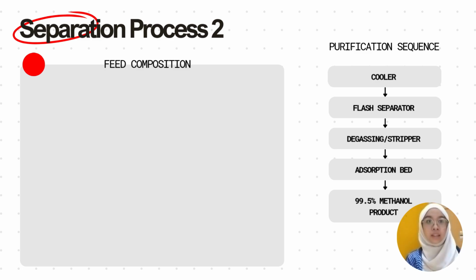2019. So from this table, we can see that even though the crude oil has gone through a reactor, there is still a lot of other impurities that come with the methanol. So along with methanol, there is water, carbon dioxide, hydrogen, carbon monoxide, nitrogen, and methane. The methanol is less than 10% of the entire composition. This is why we chose to go through a few separation processes before it can turn into the 99.5% that we want.